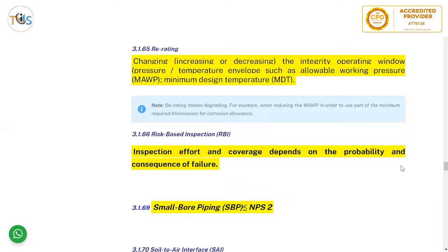That was reserved for design pressure. So you have less pressure here because you have reduced the maximum allowable working pressure and use that reserve for corrosion allowance. So it can be the standard lower pressure till the next inspection interval.